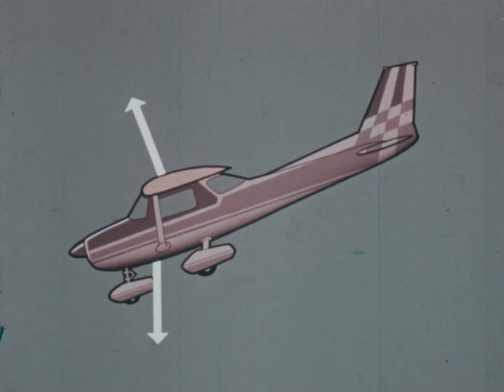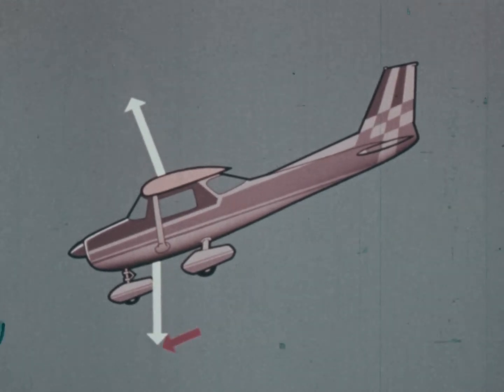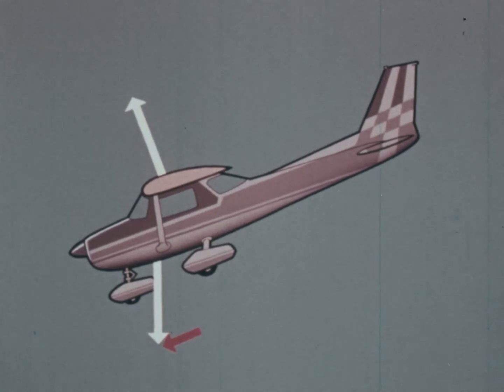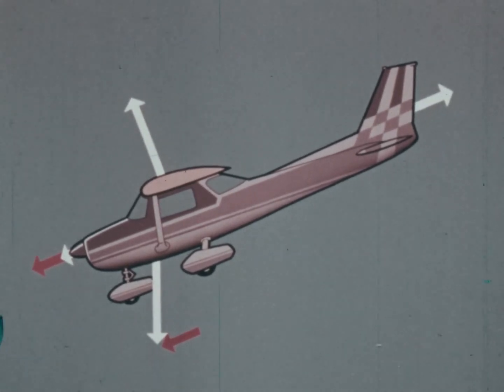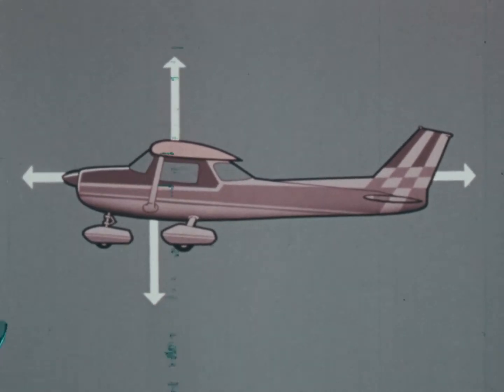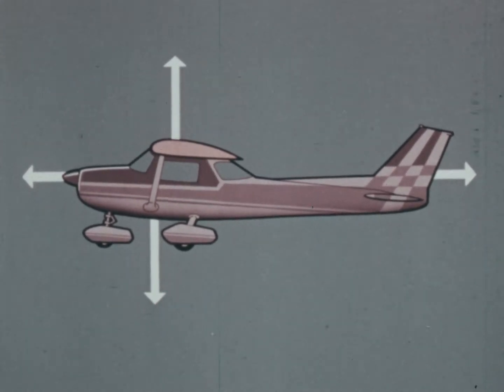But the proportion of weight acting forward along the flight path is now sufficient to act in place of thrust from the propeller and to equal drag. As soon as the airplane is leveled out again and power is restored, the 4 forces resume their normal pattern for steady level flight.